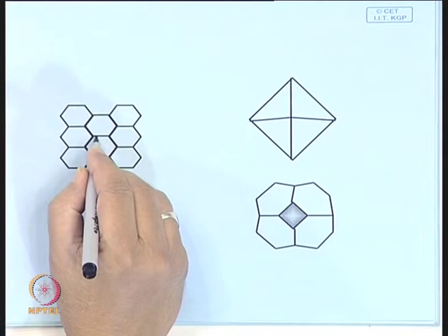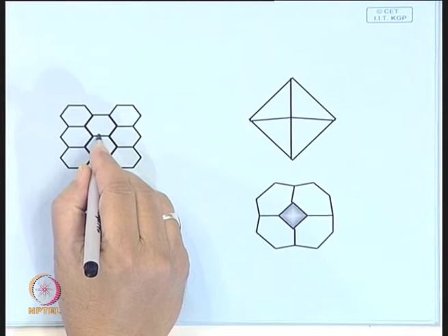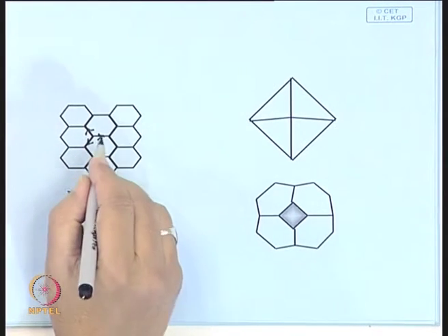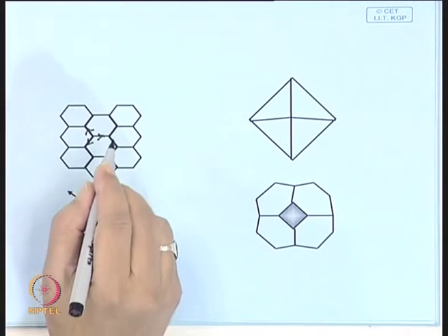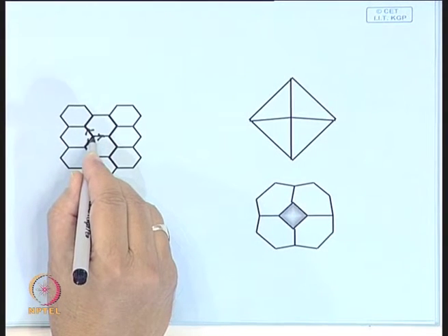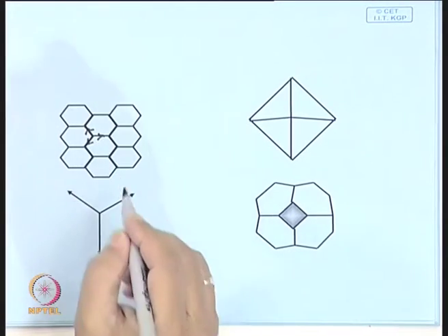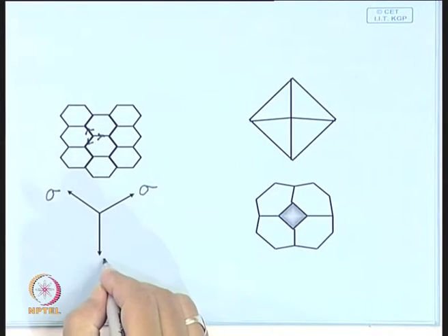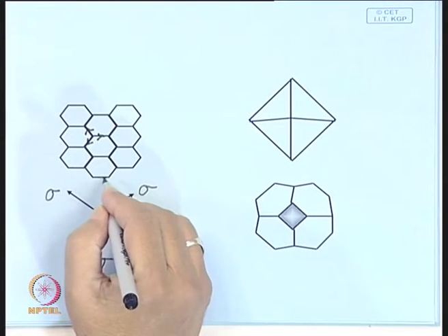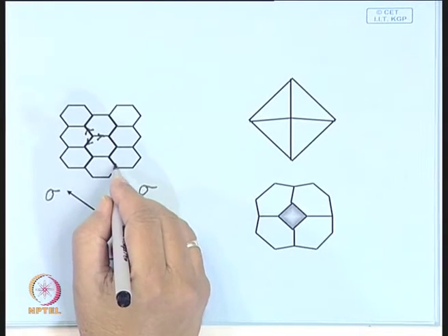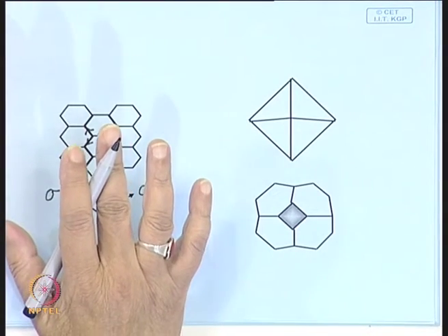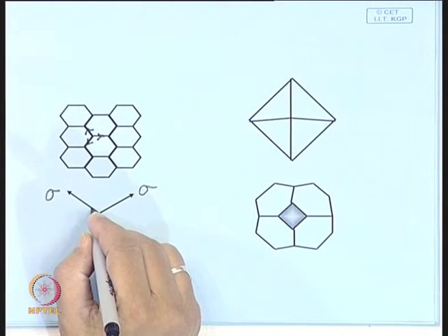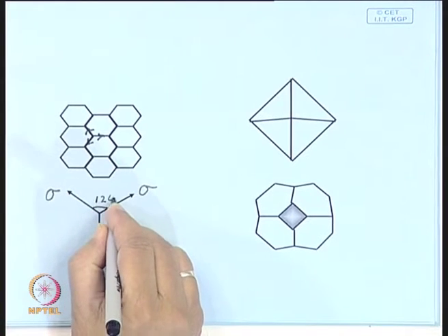Now, here we have seen this boundary has some energy associated. Each of these boundaries has some energy associated, which is called surface tension. So, there has to be an equilibrium between the energy, which is shown here. This is the grain 1, sigma, sigma. I am putting it sigma because it is pure metal, and the surface energy of pure metal, let us say, is the same. So, if it is the same, then this angle has to be 120 degree.